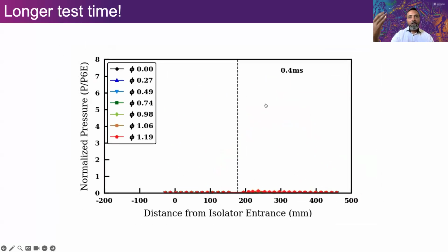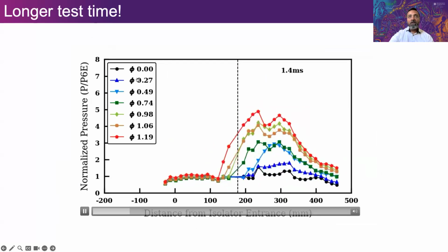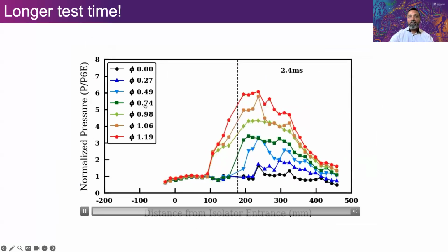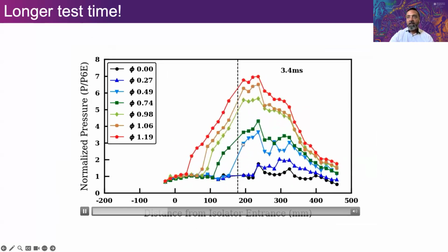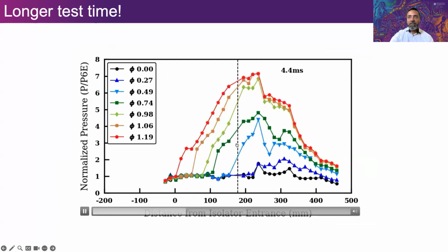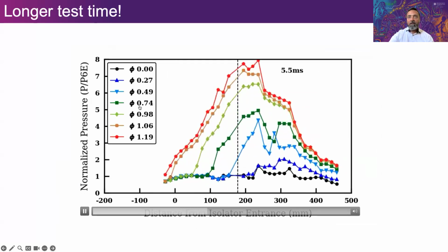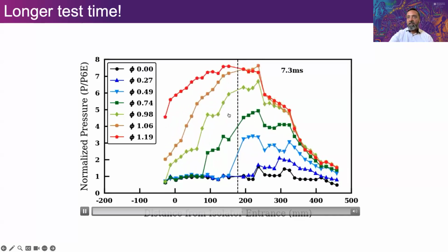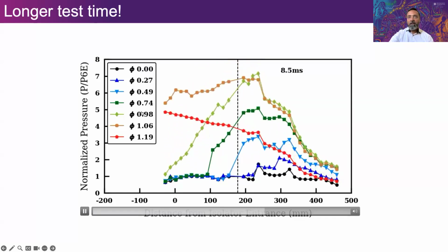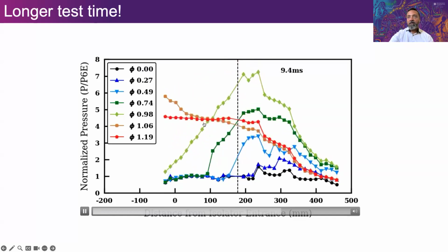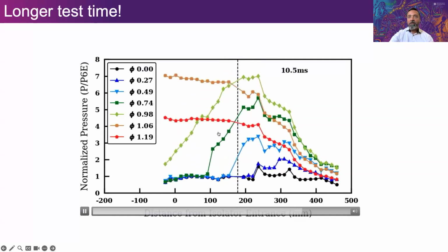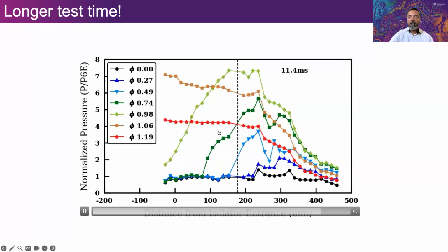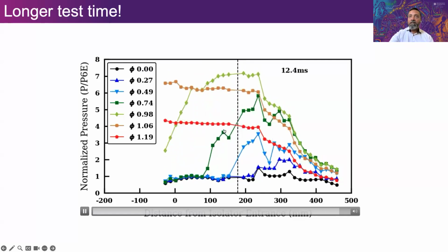Okay, so we noticed that, and then we did a series of experiments like we always do, unfueled, different equivalence ratios. Now that we know it's burning inside, when we see the pressurized, we believe it's combustion. And then at equivalence ratios where T4 would have said dual mode, we now started seeing this phenomenon where anything that's close to stoichiometric or higher, you start seeing this unstart bubble propagate upwards and spill out and cause a full unstart of the model.